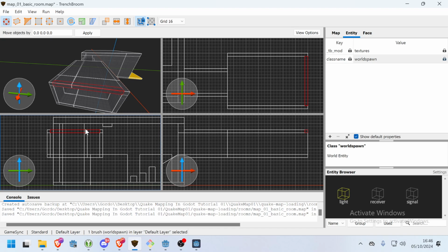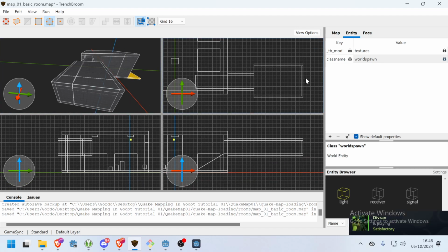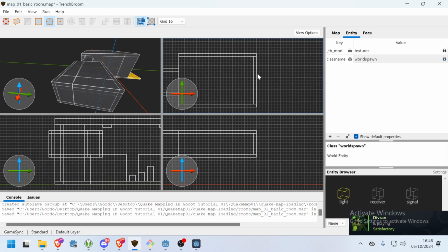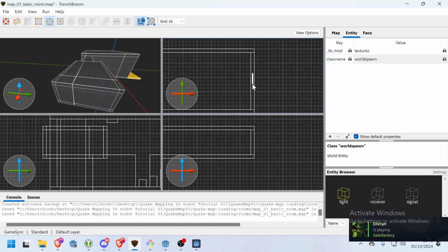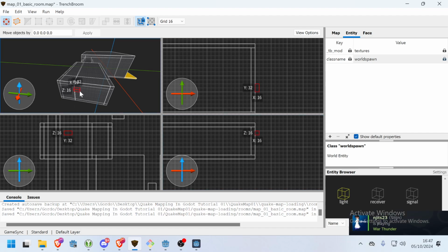Now, something that the Hammer tool could never quite get right, apparently, speaking to a guy today, was when you would cut holes in objects, it wouldn't be able to do it. It would just break, basically. So something I'm going to demo right now is I want to make a hole in this wall. I want to add a little space for a window here. Now, I could just deselect and then probably click drag, but it won't work out the projection correctly, so we'll do this instead.